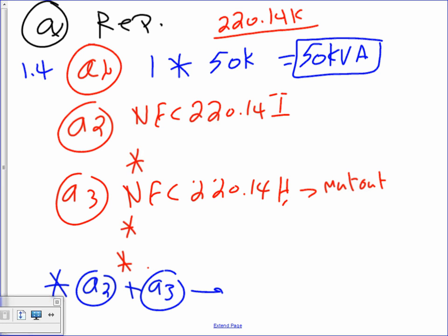This step is 1. NEC 220.14, I will tell you guys, for every receptacle that you have in your building, we call it actual. For the actual stuff that you did, 500, anybody knows what 500? We have 500 receptacles that we install in this building. Each receptacle will be at 180.